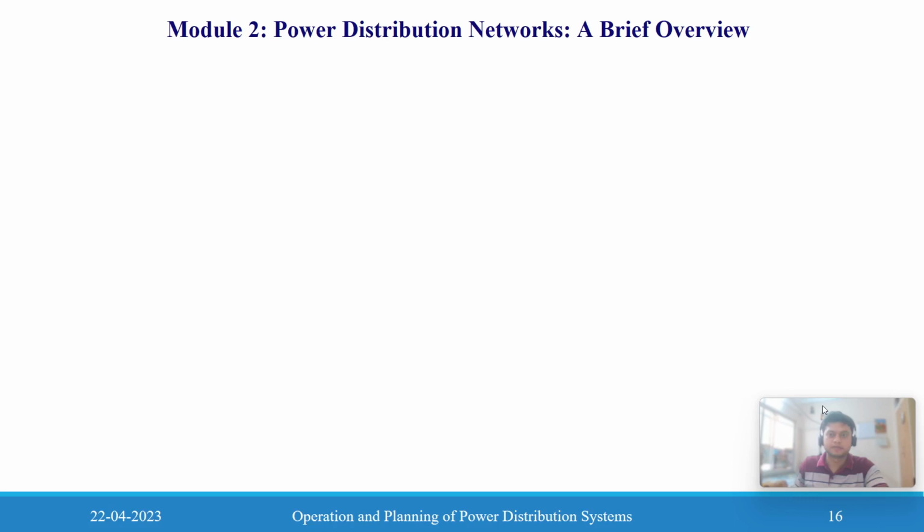So we will see this optimal power location. We will see what our objectives are, meaning total power loss. We place the distributed generation so that we can reduce the total power loss, or we can also increase the reliability of the network. It depends on our objectives.